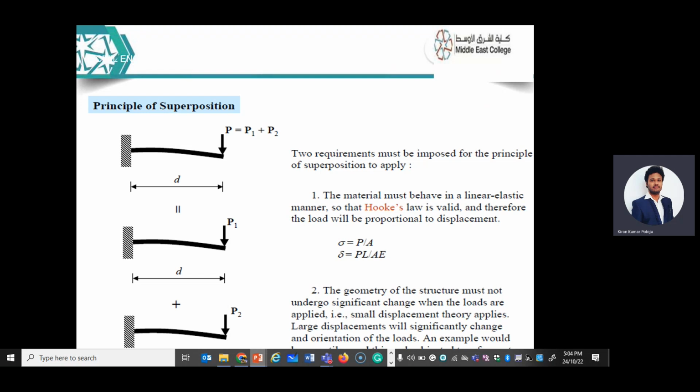In today's lab, we are going to do a tensile test. All of you please listen, because some of you are having lab today and others tomorrow. So for tomorrow also you need this explanation, right? So I will explain how to do the experiment, for today and tomorrow. The experiment we are going to do today is the tensile test. In that experiment, you are going to determine stress, strain, Young's modulus and tensile strength.